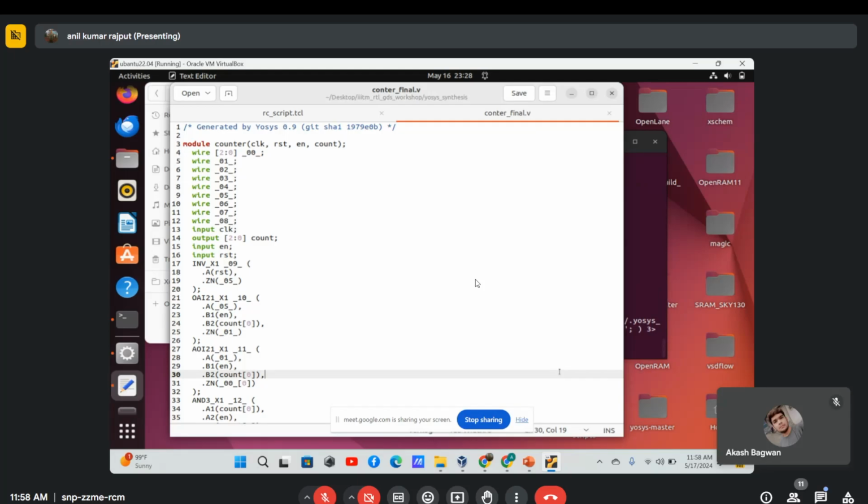So this is a gate level netlist. In the timing analysis, you can see at what frequency your structure is working properly, and what is the maximum frequency at which it works properly. In this, they analyze the critical path, meaning the first critical path from the input, through the many paths, to the output. How much delay they require for that first path delay, from that they calculate the frequency. At this frequency, your design works perfectly without any worry.